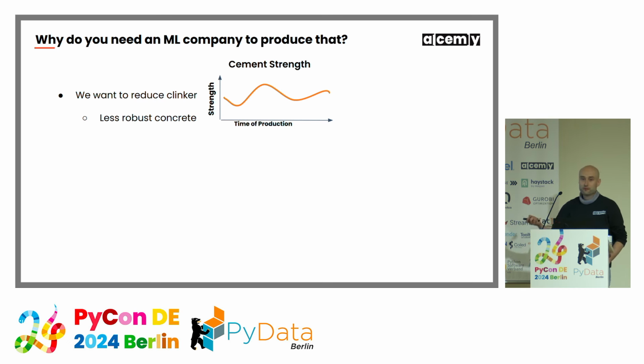And the reason is, I mean, it's a material coming from nature, right? It's made out of limestone. Every cubic meter of limestone might have a different mineralogy and chemistry. So the cement that I produce on a Tuesday might have slightly different properties than on a Wednesday. And so the Tuesday cement might not get that strong, but the Wednesday actually does because I have better limestone.